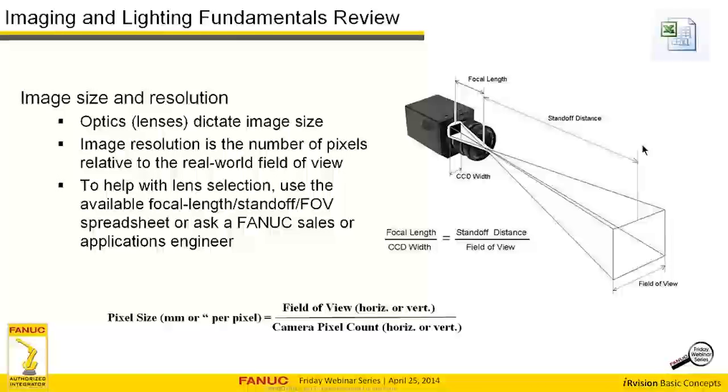A little bit about imaging and lighting fundamentals. So there's a standard relationship to figure out your field of view. Of course, field of view is important. You want your field of view to only be as big as it needs to be. How big is the feature you're going to be looking at? How much is it going to move around? Maybe add 10 or 20% to that. There's an equation here where you can figure out what your field of view is going to be.